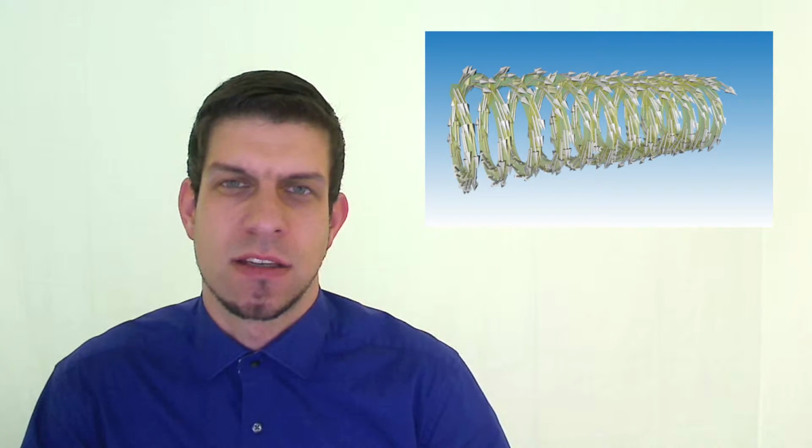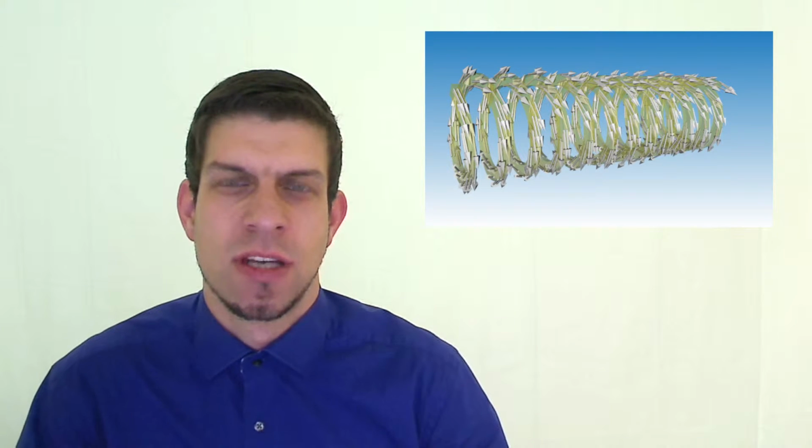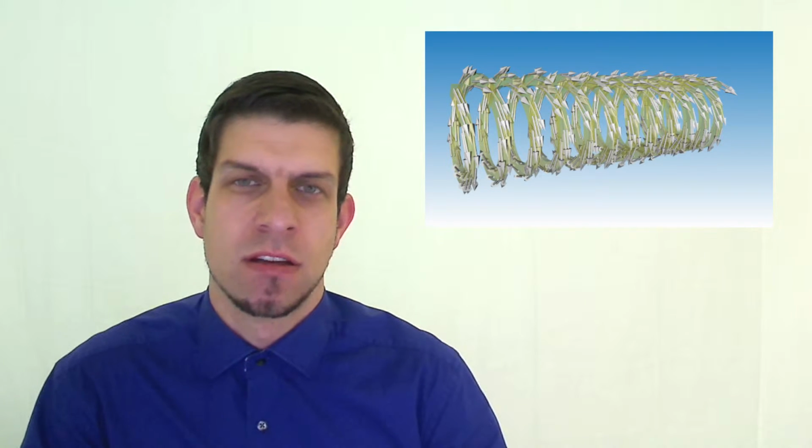If you imagine, for example, you've got a conducting device, and you've got input areas and output areas for the current that should describe the current flow in your conductor, then there will result a certain current direction. And that current direction you are now able to use, for example, prescribing a transversal isotropic material behavior to the conductor region. Maybe it's not a conductor in your case, but you can also use that directional coordinate system for that use.